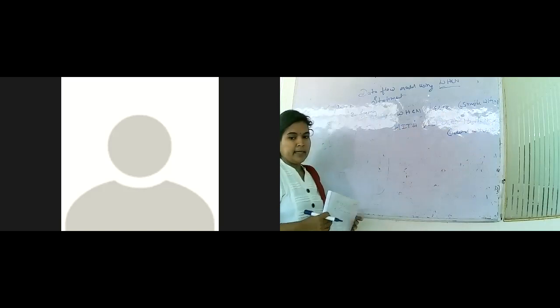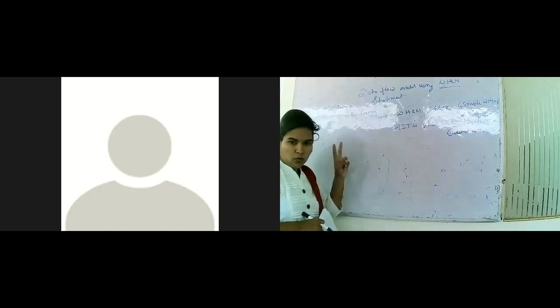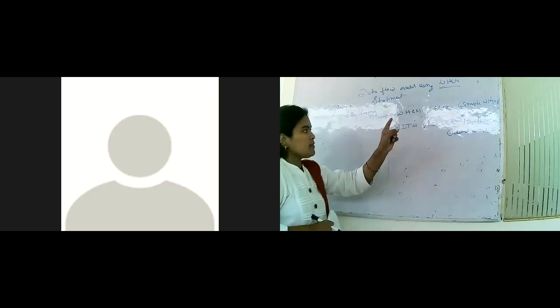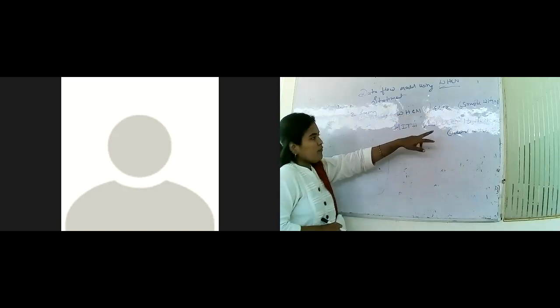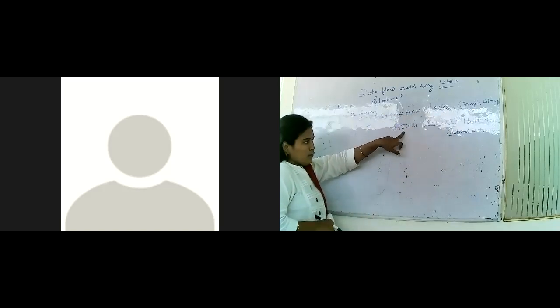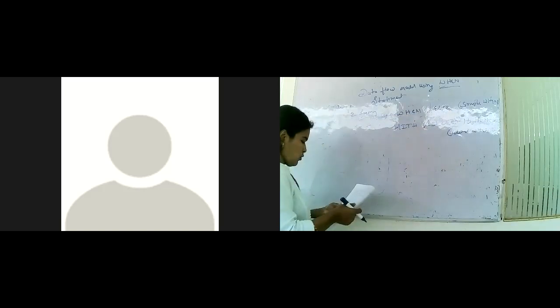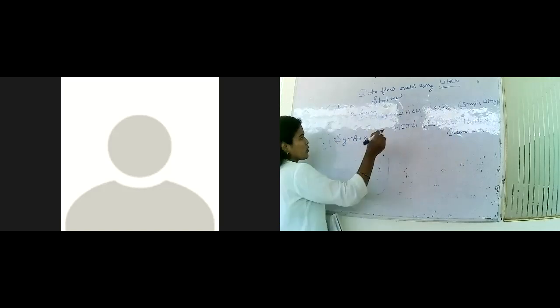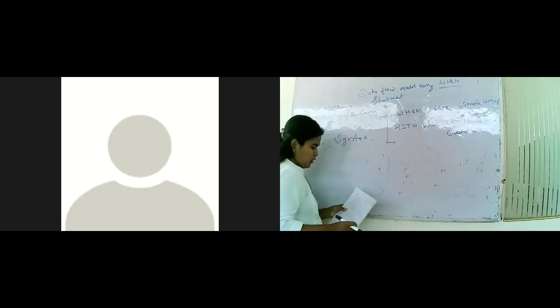So now what I am telling you is that in data flow model using the when statement, we have two forms, simple when and selected when. In the simple when, you have when slash else. In the selected when, with select when. These are the two forms. So we will go for the first syntax. If you know the syntax, then only you are able to write the program. So first I will tell you the syntax for this statement.